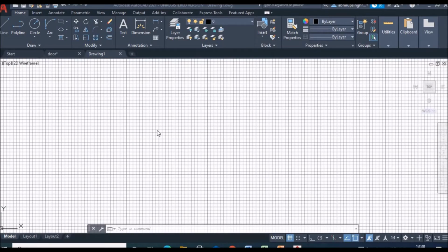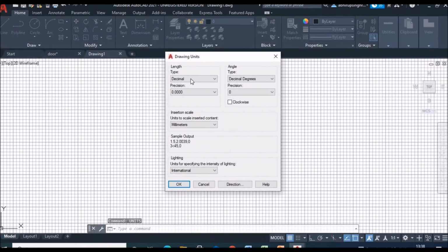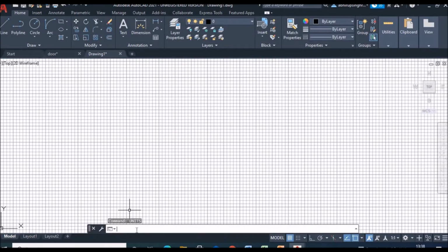We are going to do the revolve command today. So as you can see, we are on the drafting and annotation mode. Let me set my units and limits first here. I am setting it in architectural precision 0. Remember to keep the insertion scale at inches. Okay, I'll set my limits 0, 0 and 100 feet, 100 feet. And I do Z enter, A enter.